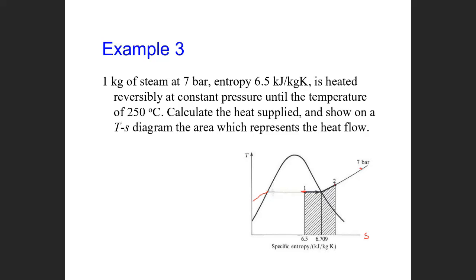Okay, and we need to calculate the dryness fraction with the given one. Similarly, we calculate the dryness fraction, then we can define whether state 1 is superheated or wet. If it's wet, we need to calculate the dryness fraction. And also we check from the table, this is superheated. It's superheated. And for state 1 it is wet.